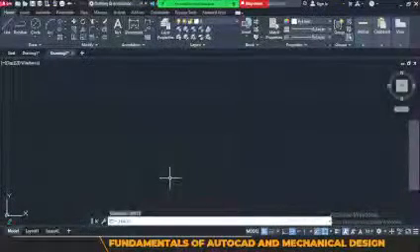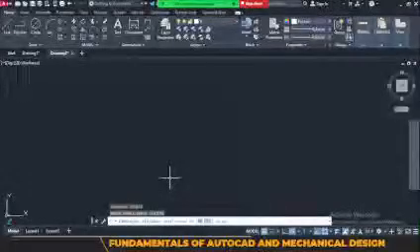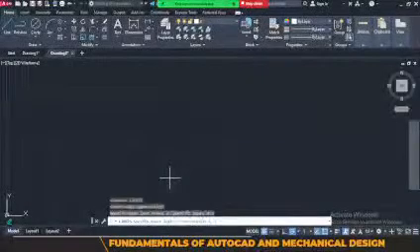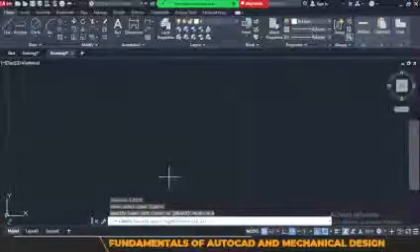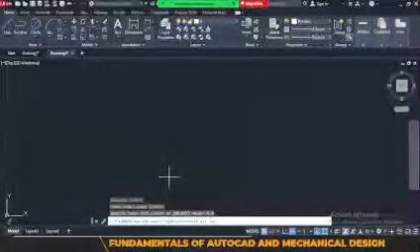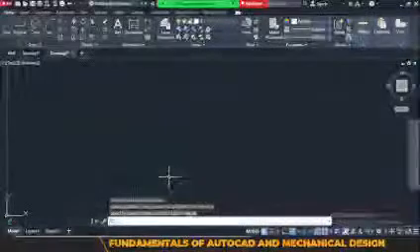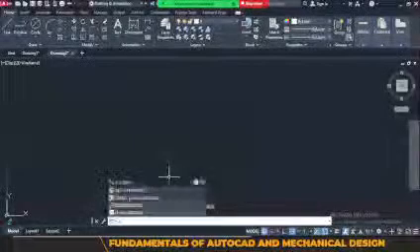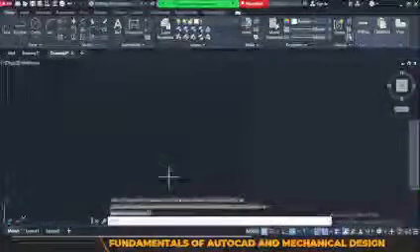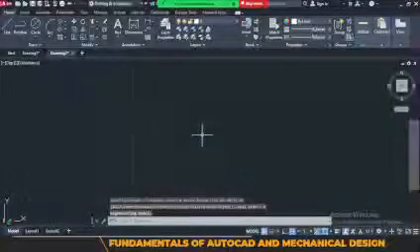Then limits, hit enter, 0, 0. I'm going to use 20, 20. Zoom, enter, all. Okay, I'm good to go.